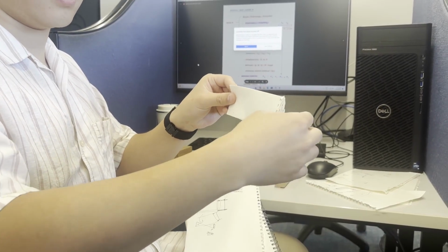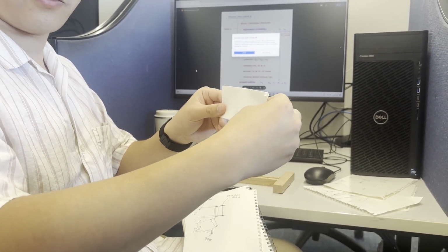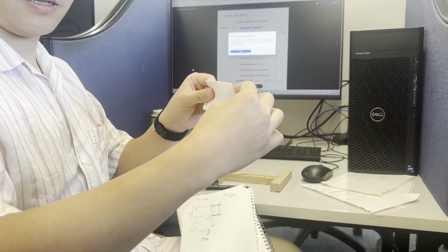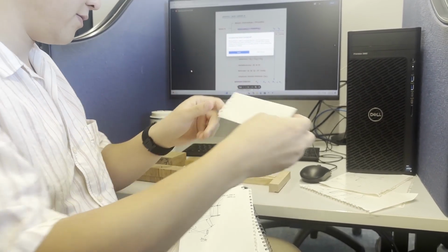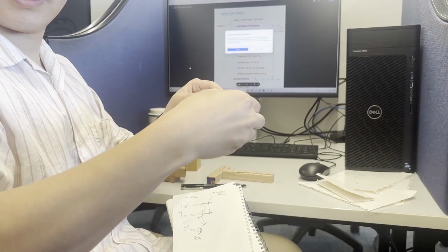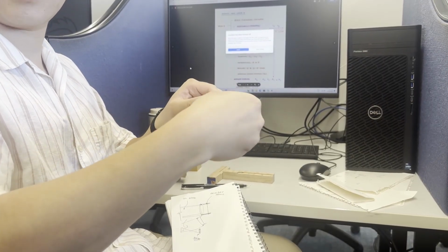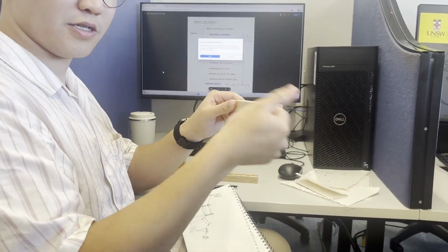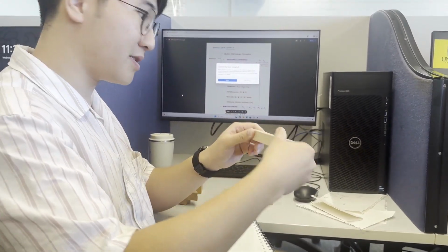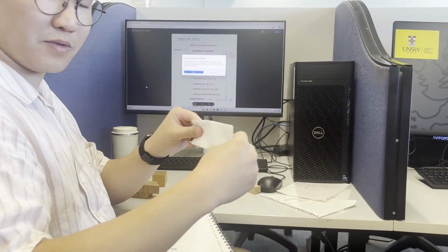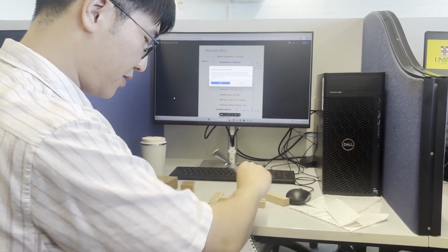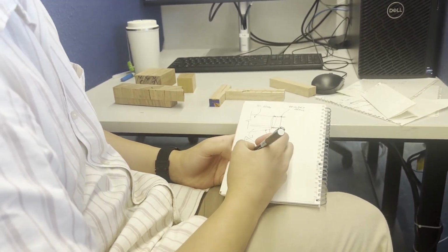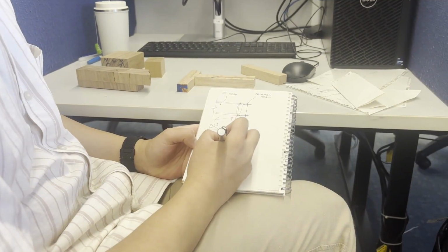Oh, not really, that's not really true. But the idea is, an I-beam is really bad in torsion, right? If I twist an I-beam, it's going to twist really easily. But a rectangular block is a lot stiffer, it's much harder to twist. Hollow sections and stuff like that are much harder to twist. I-beams are incredibly easy to twist. And so this is a really bad design, okay? No offense.